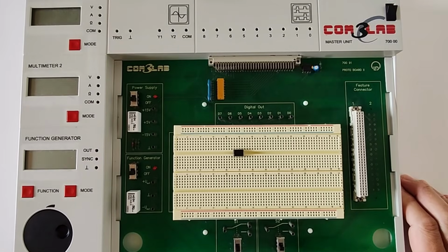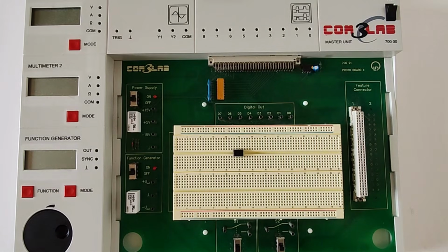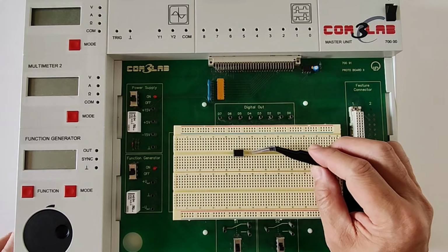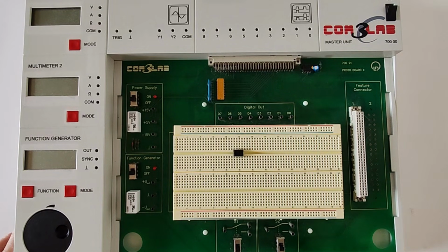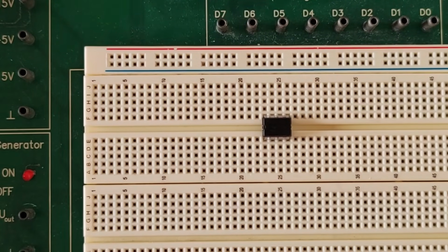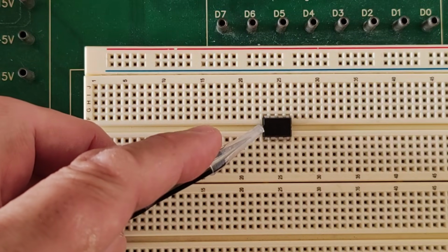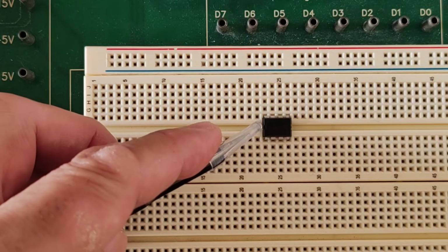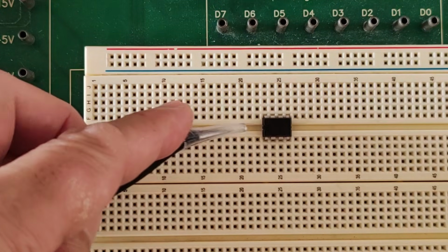Let us now construct our Astable Multivibrator circuit using this COM3 Lab protoboard, just like what we did in our previous video. The NE555 Timer Integrated Circuit I've already inserted here on the breadboard. As discussed earlier, the pin configuration of our NE555 is very similar to our LM741, the operational amplifier integrated circuit we used in our earlier videos. The notch I referred to earlier is located here on the left side of this IC.